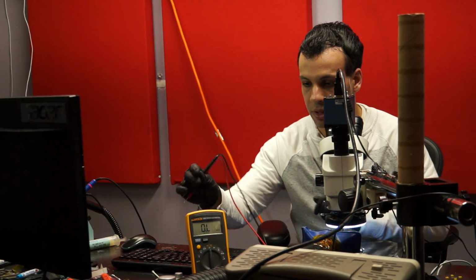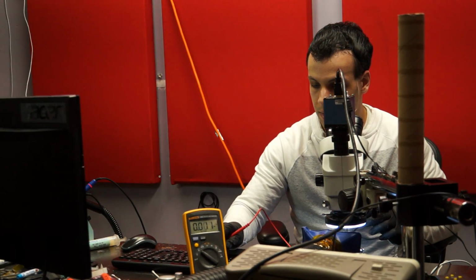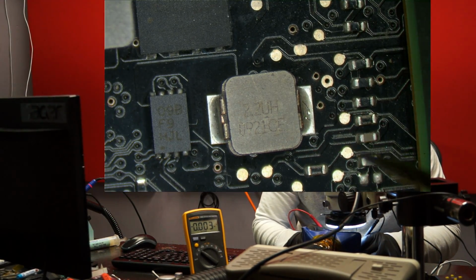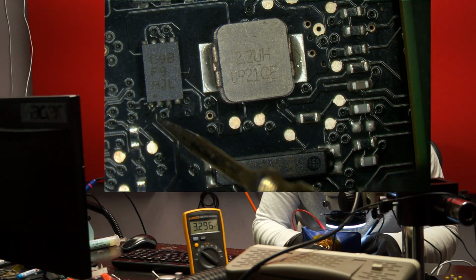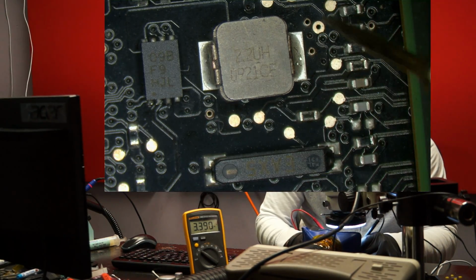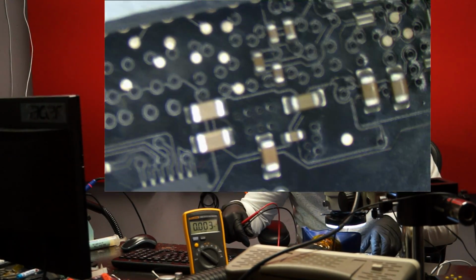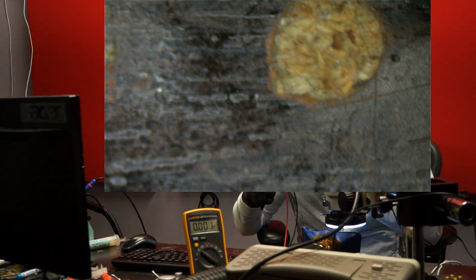Let's see. PP3V3_S5. Gotten anything? PP3V3_S5 is supposed to be present on the input of this IC. So it's there. Alright. Enable. There. PP1V05 is there. Okay, so we've made some progress here. This is stuff that I didn't have a minute ago. Which begs the question, is this thing just turning on and I don't see the fan spin?